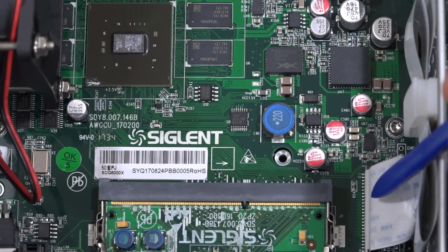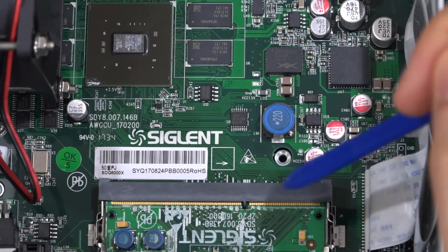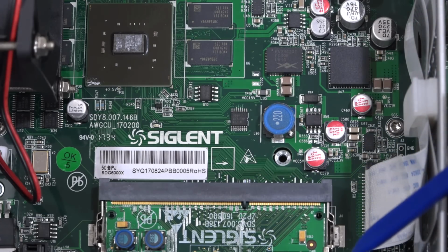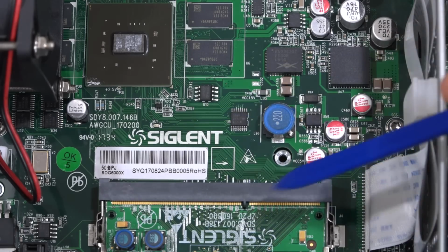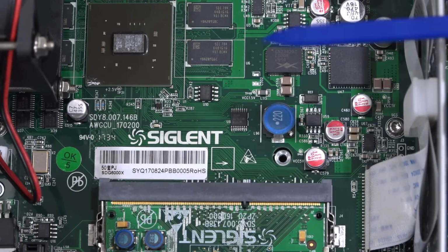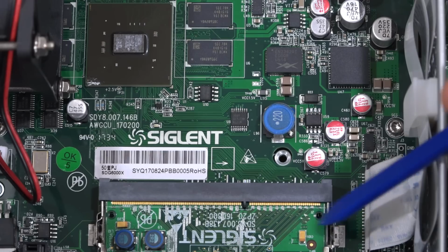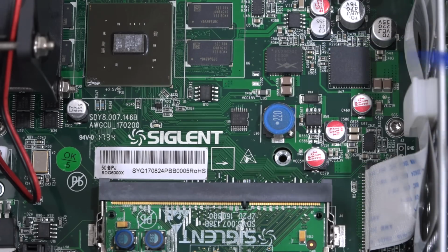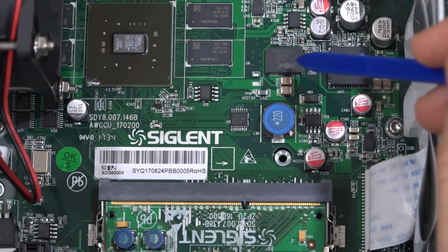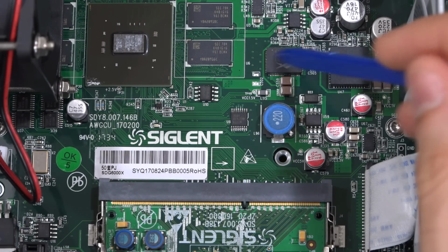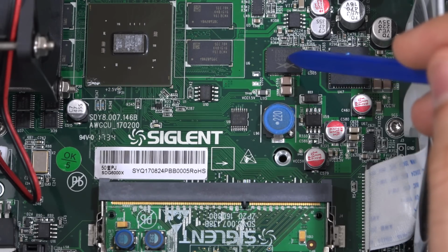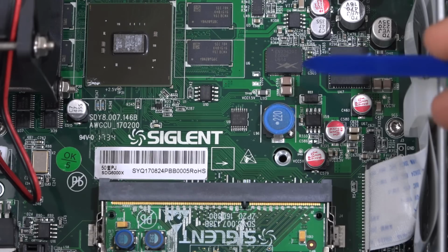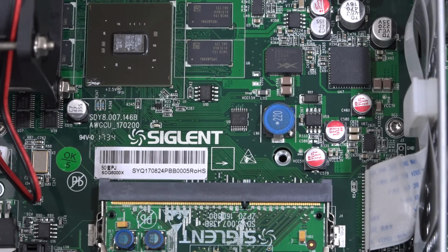Now there's also the interface to the LCD screen, so some of those traces are going underneath from the LCD screen as well. But nothing really interesting over here aside from all the digital lanes going back and forth between the FPGA and the main board over here. Here we have a couple of components. These are Altera Enpirion DC-DC SoC converters. These have everything built into them. I think I've talked about this before. They have all the required circuitry for power conversion as well as built-in inductors. These are becoming quite popular because of their compactness, efficiency, and ease of use being fully integrated SoCs.